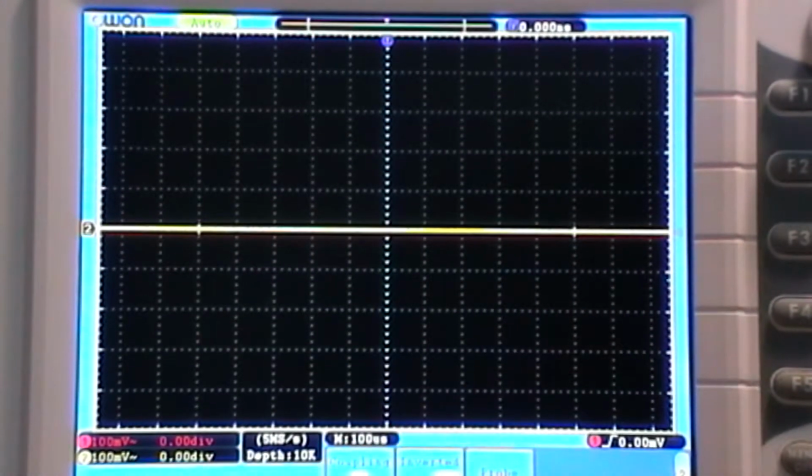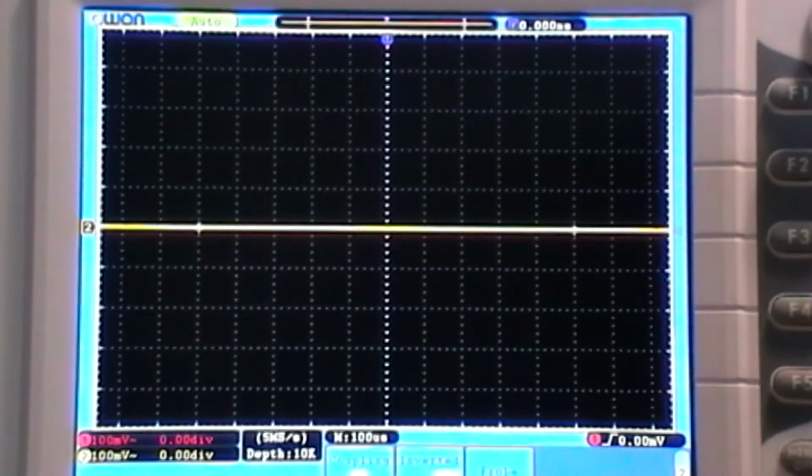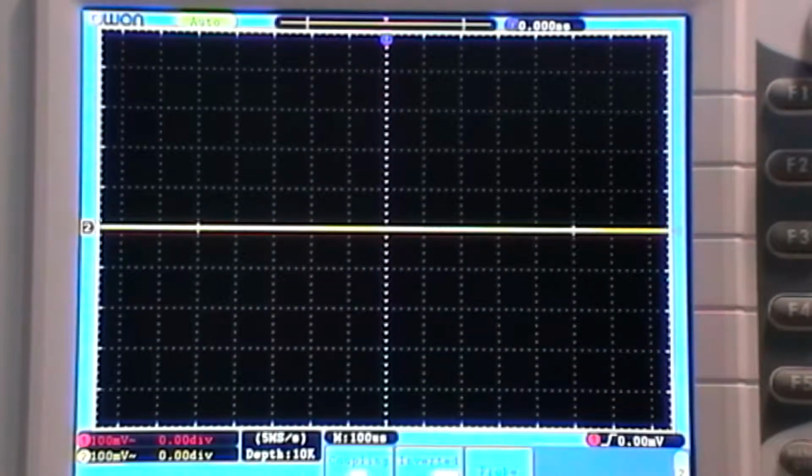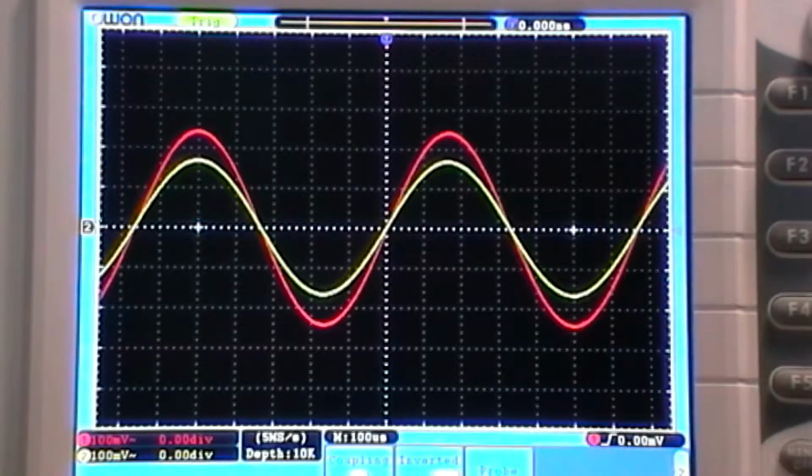Now, when I looked at this, I set this up so I should supposedly have a high pass cutoff of 723 Hz. So that's going to get rid of all my low stuff, and then I'm going to have the bandwidth that I want up to the cutoff point of 3.38 kilohertz, and then I'll have my low pass filter attenuating everything else. So I suppose midpoint 2 kilohertz or 1.5, 1.6. I'm going to set it to 1.5 kilohertz. I'm going to start it there and see what I've got.